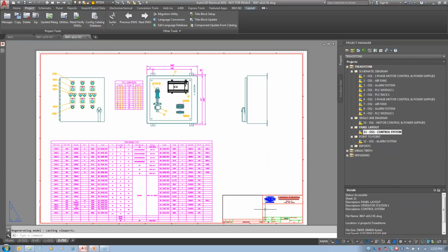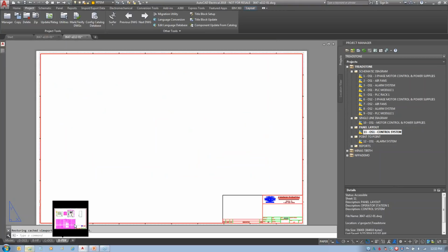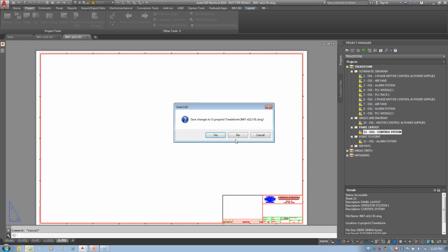I did this for one reason. I've noticed when I'm doing things on the internet, most people think that you can only have one title block per drawing. And that's not true. It's one title block filled out, but I can have different title blocks of different sizes for different types of prints, all within the same drawing, and the title block update will recognize that. So that's the reason I wanted to point that out. But right now, the only one we've assigned is the T block D.